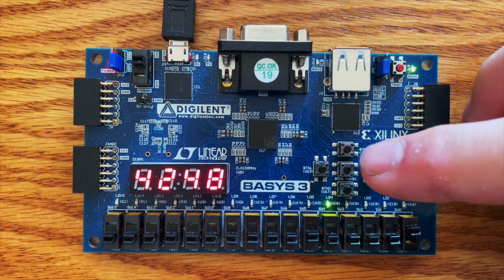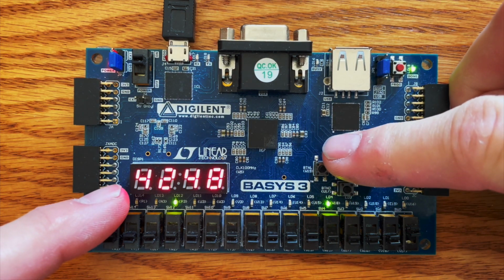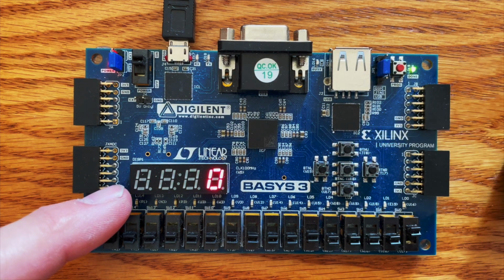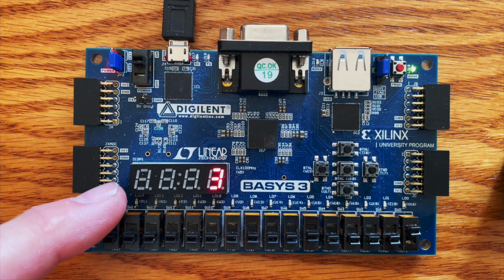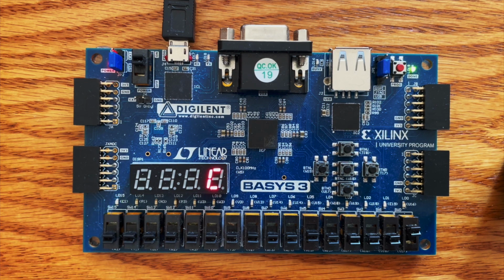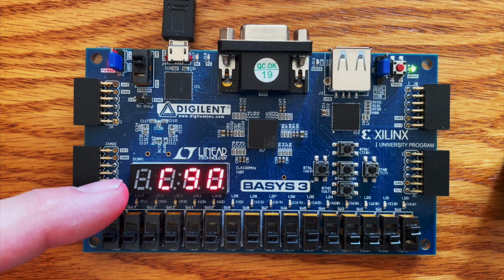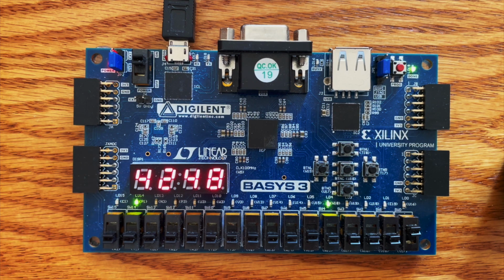You'll see the quotient being computed bit by bit on the 7-segment display. Since we're dealing with binary 16 values, the quotient significand will be computed to 13 bits. Then, if the quotient significand is not normalized, as for this case, you'll see the significand shifted one more place to the left, and then the final cycle will display the computed result.